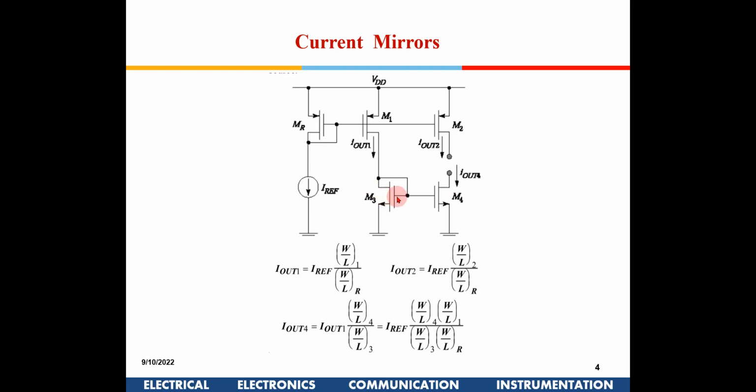No, I told you, the problem on the schematic level you may not find, but when we are doing the layout, I told you all the substrates will be connected to the ground. If there is a voltage available on your source and it is connected to the body, you might get a 0 there. From the layout point of view, we should avoid that. Okay, sir.